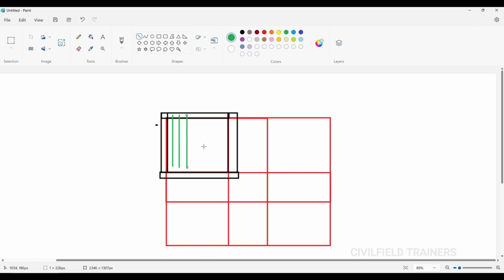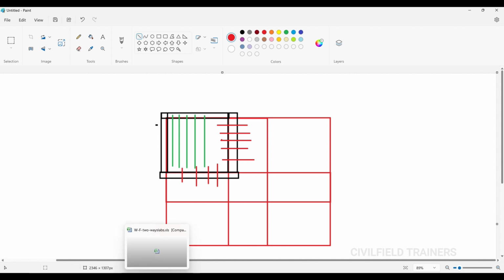Whereas for these two conditions, that is my continuous sides, I'm going to get some more reinforcement here, right? On the top side, negative moment. So basically the code book is telling me that wherever your beam is ending, the slab is ending over there. And wherever after the beam you have one more slab, you have a continuous rebar going into that particular slab. So for that I have got two values.